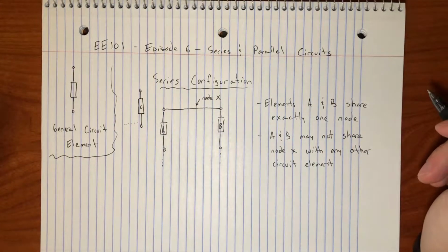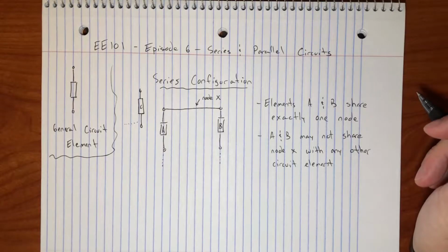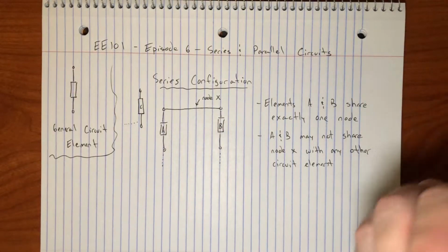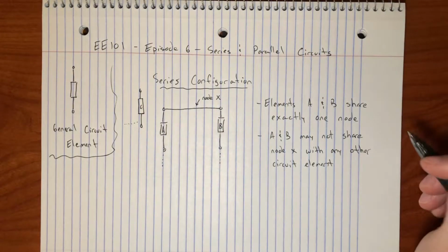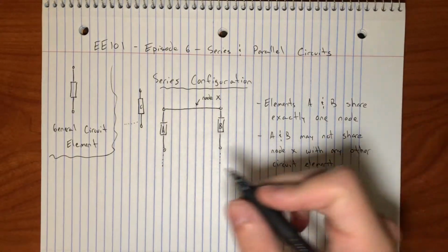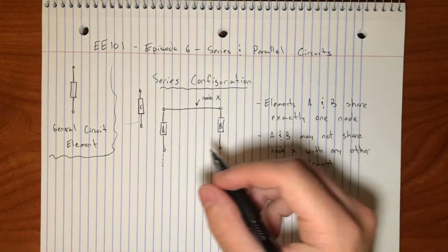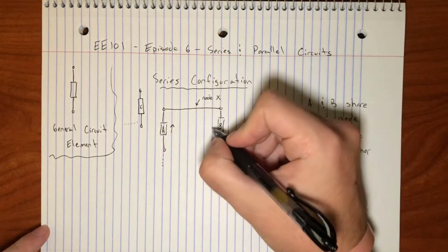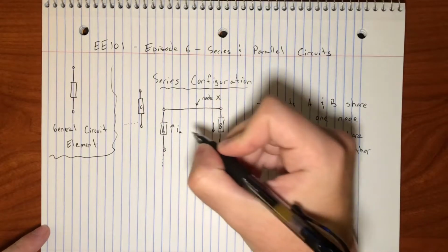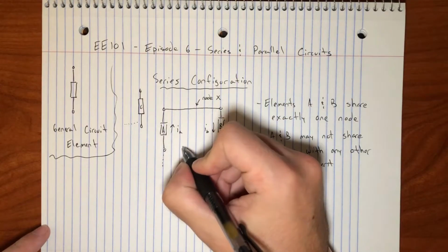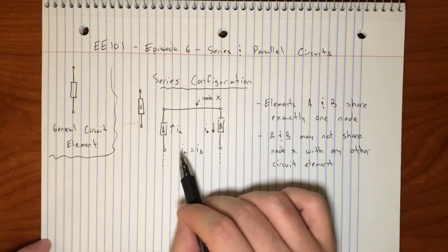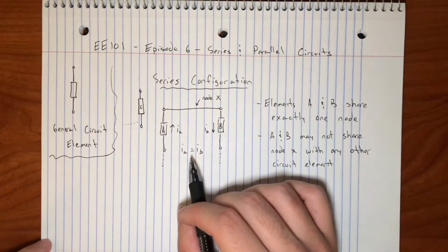That's a series circuit. Now, one thing to keep in mind here is that because they're connected in series, and I want you to think back to my video on KCL so that you start drawing parallels and connections here, well, I think what's probably very clear to most of you is that because they're in series, these two elements have to share current, right? So the current through these elements then, IA and IB, are equal. And so this is probably the idea that you're going to apply practically in your circuit analysis.